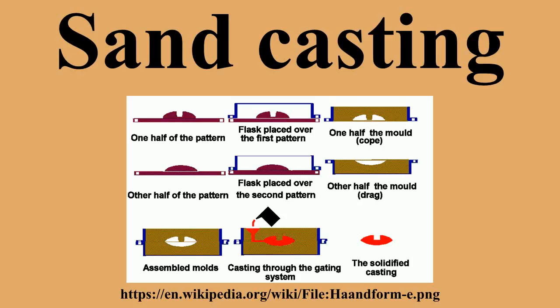During casting, some of the components of the sand mixture are lost in the thermal casting process. Green sand can be reused after adjusting its composition to replenish the lost moisture and additives. The pattern itself can be reused indefinitely to produce new sand molds. The sand molding process has been used for many centuries to produce castings manually. Since 1950, partially automated casting processes have been developed for production lines.